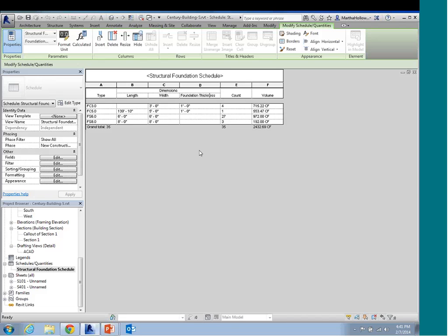And it's not found in the spot footings. But I want to have just one thickness list right here instead of having to do a foundation thickness and then switch it over and have another one for the spot footings. So instead of using this one, I'm going to create a new one that I'm going to then make sure is available in all of my footings.